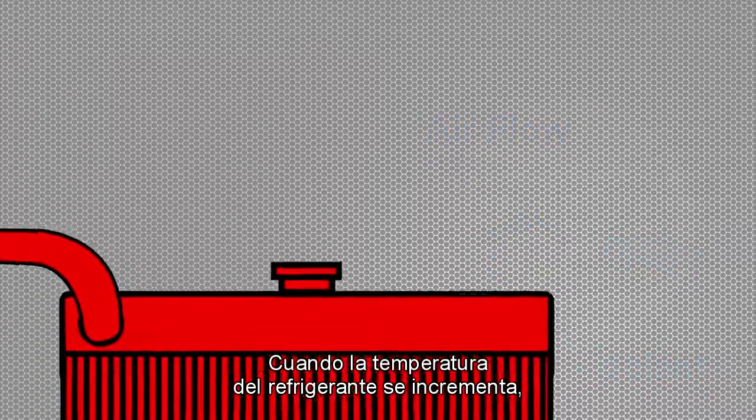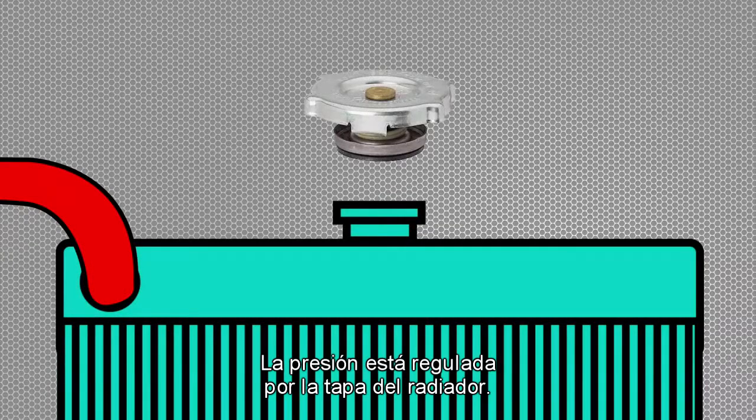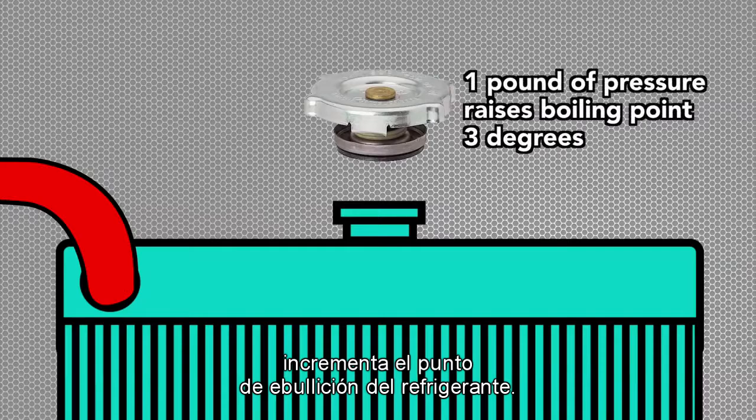As coolant temperature increases, so does the pressure in the cooling system. This pressure is regulated by the radiator cap. Correct system pressure is required for proper water pump seal lubrication. Increasing the cooling system pressure raises the boiling point of the coolant. For each pound of increase, it raises the boiling point 3 degrees Fahrenheit.